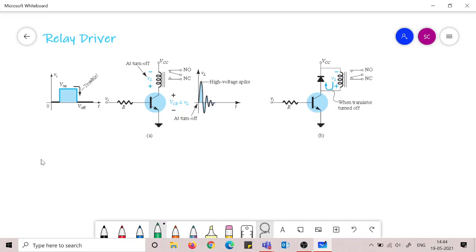This signal is fed to the input of the relay, and then the relay trips. We say the relay trips. So the relay tripping means it cuts off that part of the circuit. And whenever the circuit again becomes healthy, that means the fault condition is no longer there, what will happen? The signal which was generated due to the fault will also no longer be there. And in that case, this signal which is coming to the input of the relay driver will no longer be there, and the relay will again reconnect. So it had opened the circuit, now it will reconnect the circuit.